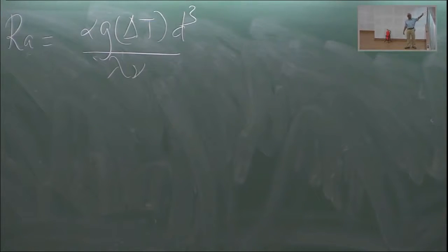Why do we have 1/3? Because that is the critical, as I said, if I want to have a stable boundary layer which is essentially conducting, then the critical Rayleigh number has to be lower than 1708. It is not that it is exactly that, it may be, may not be, but it is some number which is less than 1708. I mean, 1708 seems to be very precise.